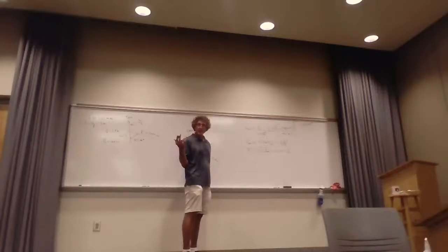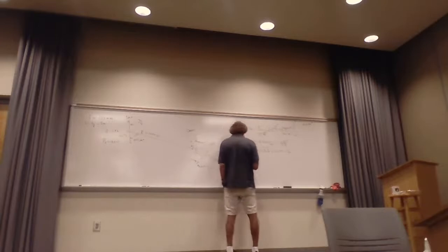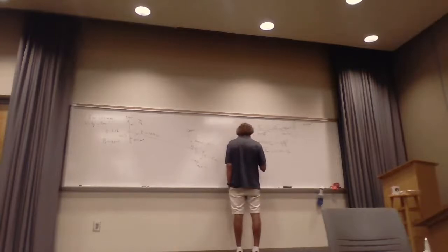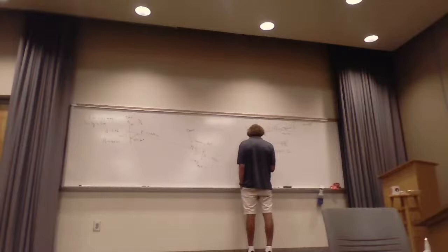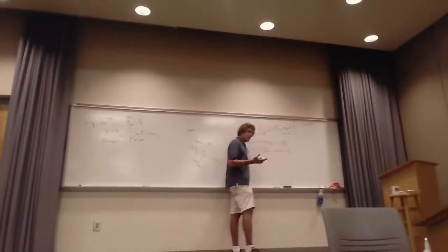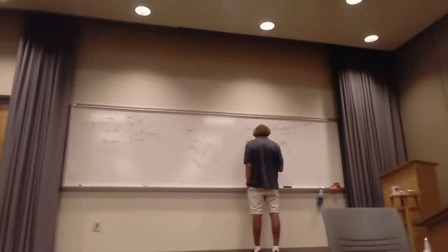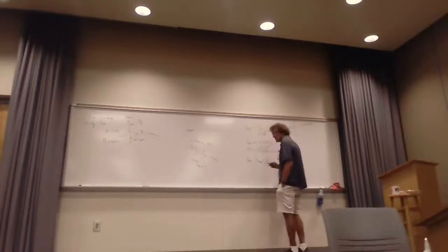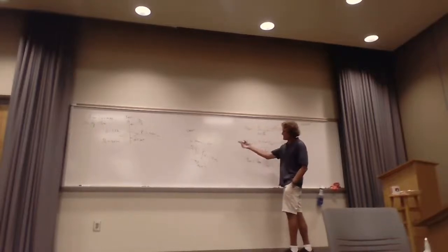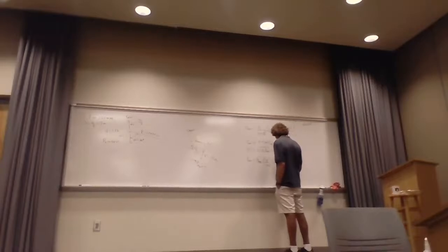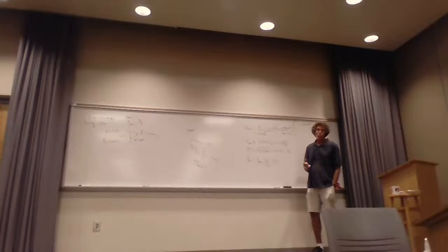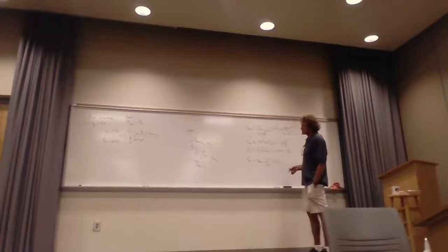It's the maximum possible power received by antenna 2. Yeah, P received. So now we want P received. This is the one where you take the average power density, right? And now you need the size of it, the aperture, correct? And the aperture is going to be lambda squared over 4 pi, times the gain, right? Since it's 90 degrees on that one, the gain is just 3/2, isn't it? There's no sine squared to be worried about, correct? Because it's 90 degrees. And the lambda you've got there is 3.